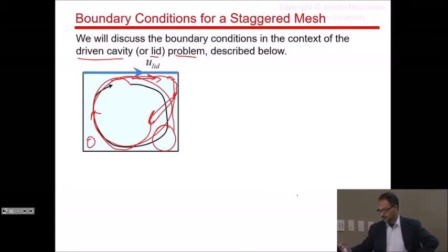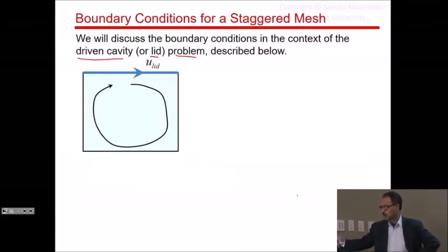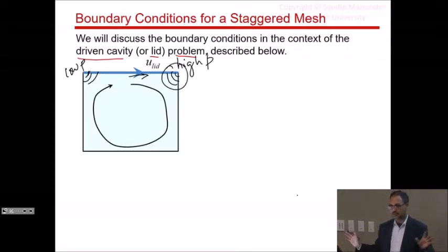Just as a brief heads up, I already mentioned that the fluid is getting dragged by this plate. So you expect that right here is going to be high pressure in that corner, because the fluid is going and hitting that corner. On the other hand, this corner here is like a suction zone because the fluid is moving out there, so this is going to have low pressure. This corner is going to have the highest pressure of everything.